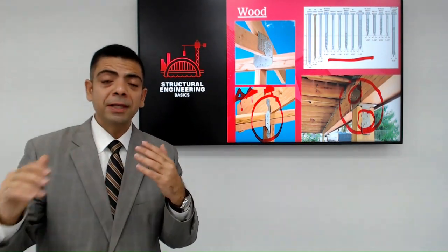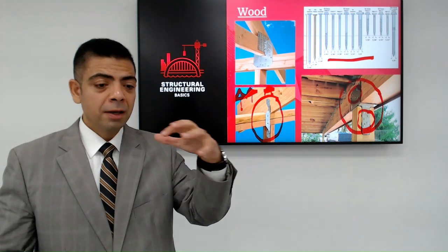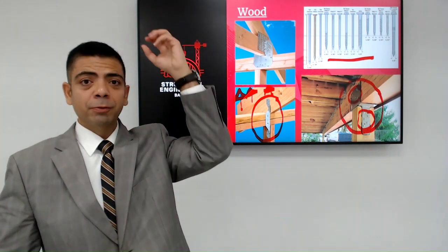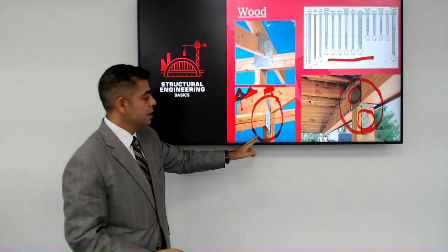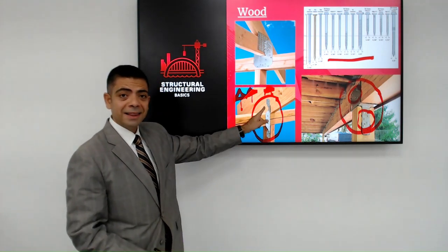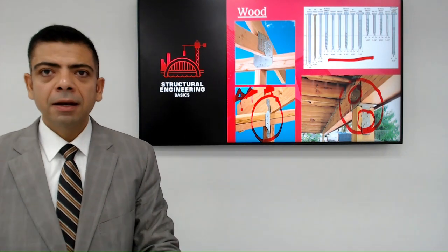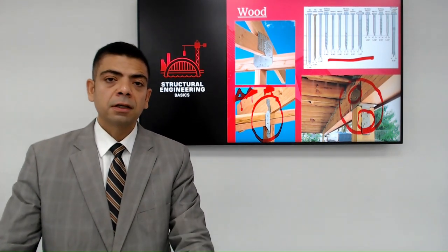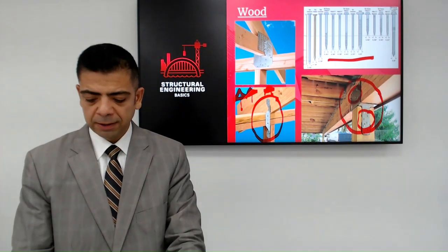Very high wind speeds create suction action on the roof. And you can look these up on videos. There are all sorts of videos of how a storm can pick up the roof and cut it clean off the rest of the building. So details like this, specifying that little connection here, can significantly help the roof stay in place under very high wind speeds.